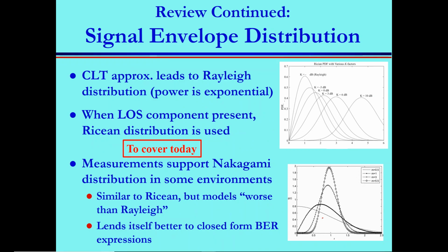After that, we talked about signal envelope distribution, and basically this envelope, you can understand it as the amplitude of your signal. We said since the signal R has Ri, the in-phase, and the quadrature component jRq, what's the amplitude of this? We said the amplitude is the square root of Ri square plus Rq square. So this amplitude of R,